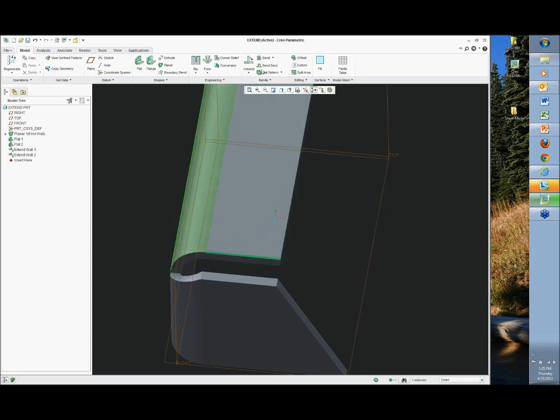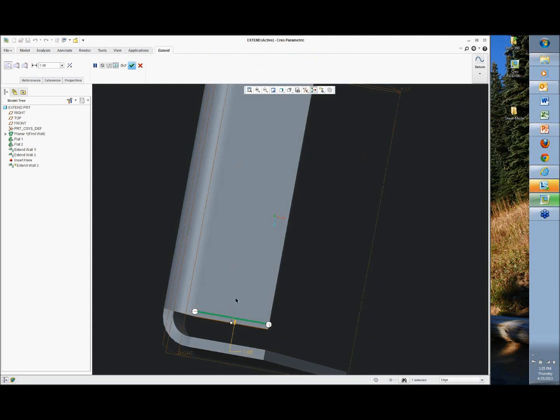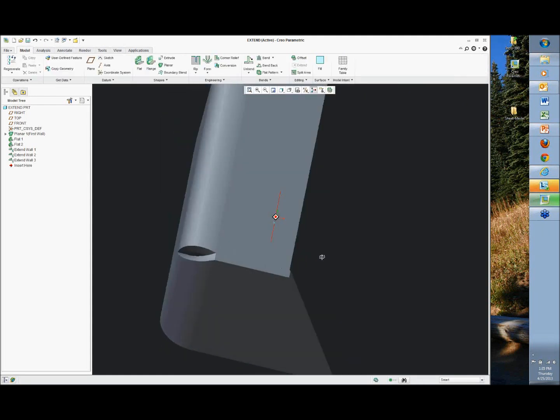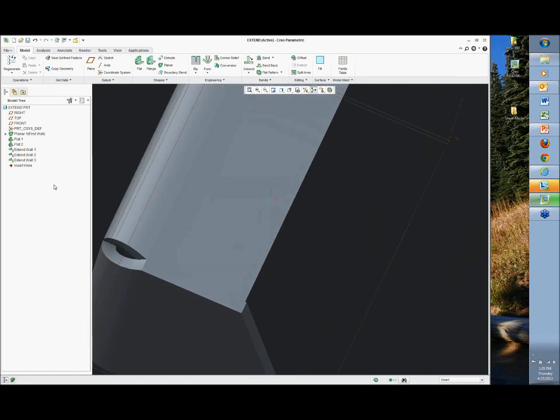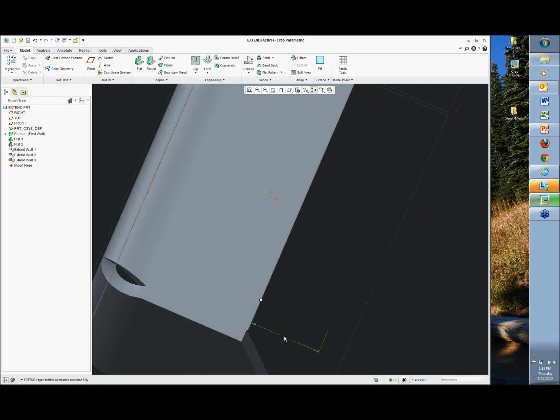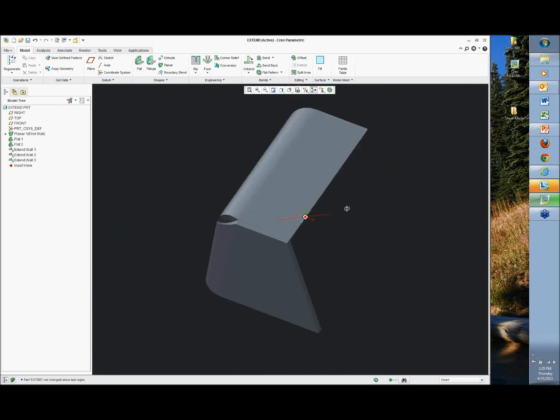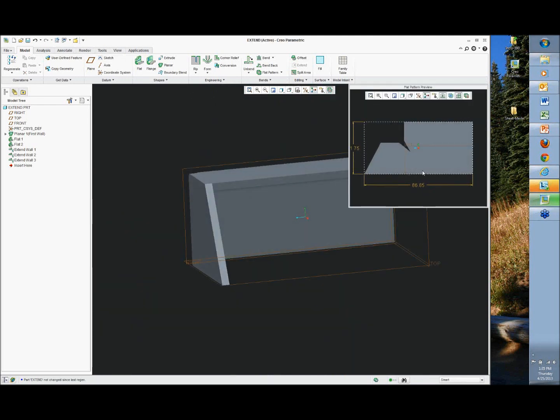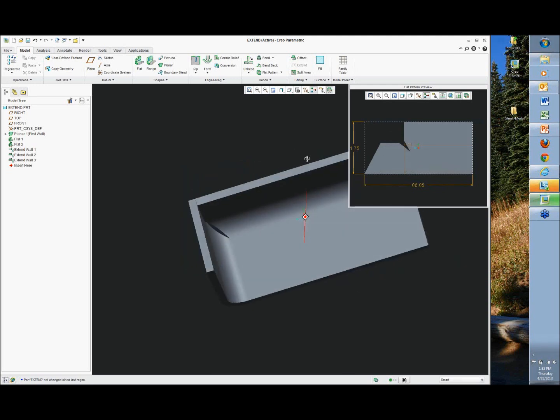And the same thing this way. So we can see how we closed it up pretty nice. You can always go back to my extend. Get that a little bit closer, and looks like maybe a hair longer. Control G, update. Look at our preview window. Bounding box, we get a nice little cut. Off we go. So again, nice extend tools.